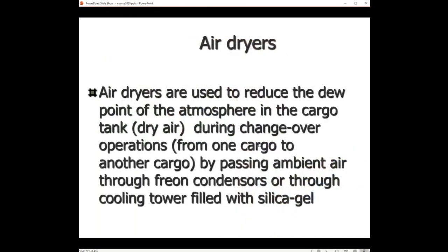Then the air dryers. Air dryers are, as the word says, equipment that will dry air. When do you need dry air? Well, there are several applications where you need dry air, like, for example, in the hold space. Please keep in mind that related to the transport of ammonia, you will fill up the hold spaces with dry air and not with IG.